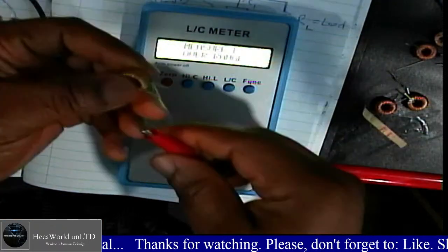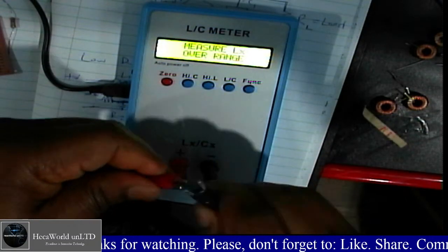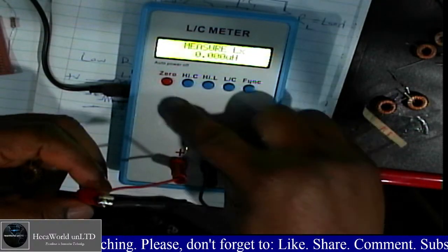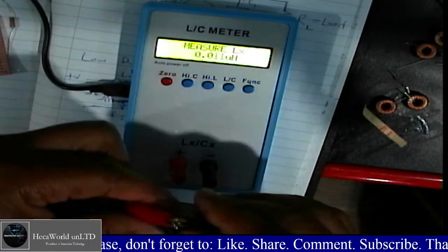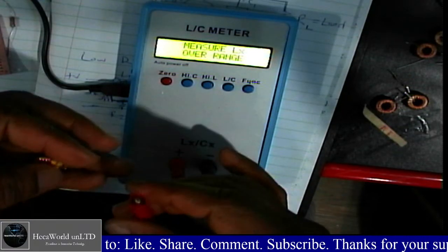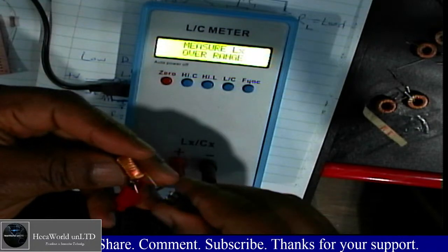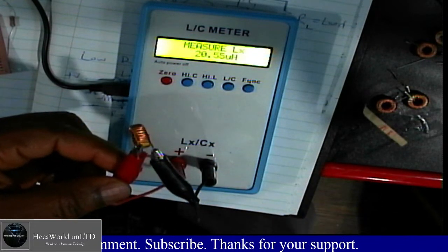Take one of the inductors, clip it here. Well, first of all, I want to calibrate. So I'm gonna calibrate, and I'll zero it by pressing it, zero it out. Alright. And then I'm gonna connect it. This is 20 microhenry.